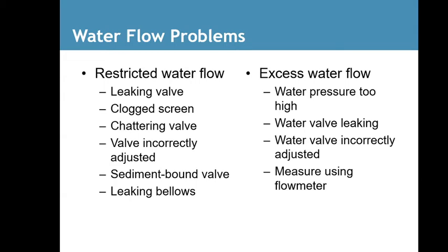Water flow problems. Restricted water flow: leaky valves, clogged screens, chattering valves, valves incorrectly adjusted, sediment bound valves, leaking bellows. Excess water flow: water pressure too high, water valve leaking, water valve incorrectly adjusted. Measure using a flow meter.